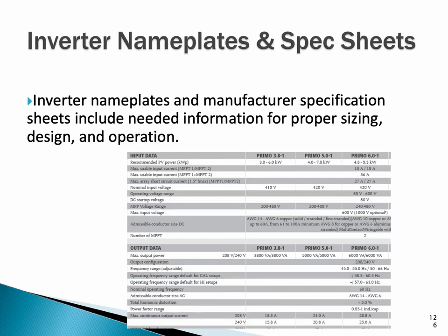But what we want to know is, what is the MPPT voltage range? Here it is right here, if I can see that. So it looks like this is around 300 to 450 volts. So the inverter wants to see that voltage somewhere between 300 and 450 to make the inverter the most optimal it can be for the given conditions.